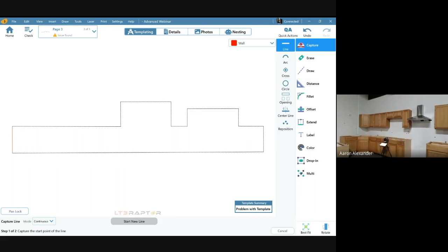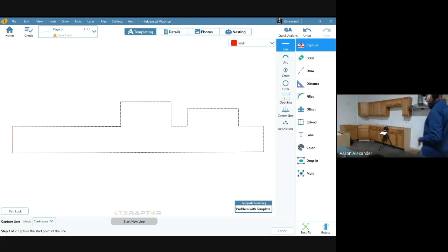So that's what we're talking about. How does this thing create our measurements, right? How does the magic happen? When we're talking about what creates a bad dimension, since you brought that up, Jimmy, let's talk about what creates a bad dimension here, right? As I was explaining earlier, capturing this line's angle in space is the most important part of this whole machine. Its ability to capture 2 points on that edge and create that edge's angle in space is how it generates these dimensions, okay?